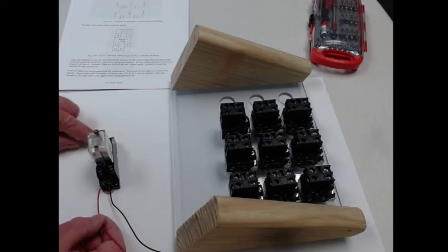So that's a symbol that it has changed, so that the normally closed contact will open. So 1 to 5 will now be open, and 5 to 9 will now be closed. Same way with the 4 to 12 will be open, and the 12 to 8 terminal will be closed.